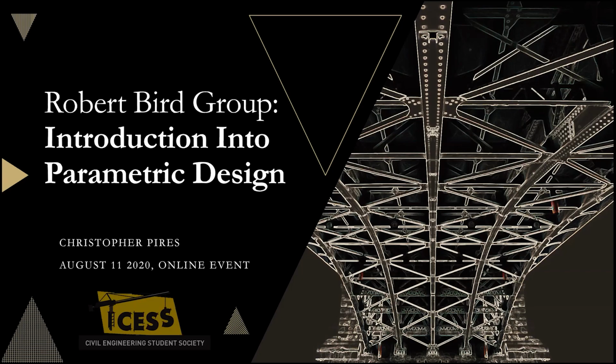I will always create structural offsets from an architectural finish. That's never confirmed by an architect all the time. What's your build up? What's that build up zone? So there's your architectural finish, and then there's an architectural build up zone, and then there's a structural element. That build up zone can always change, which changes your structural geometry.